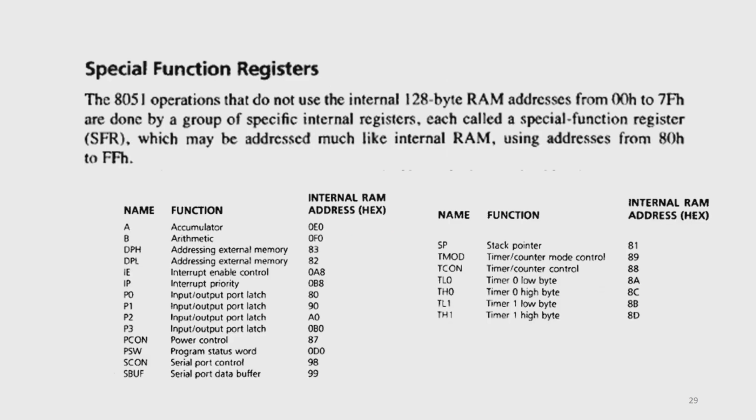And this is the main thing in the 8051 microcontroller, the special function register, abbreviated as SFR. Many of the registers are 8-bit registers, and each has a permanent internal address, which can be named as an internal RAM address, but it is not actually from the random access memory. These are registers that can be addressed, and each has a special purpose, like internal random access memory.